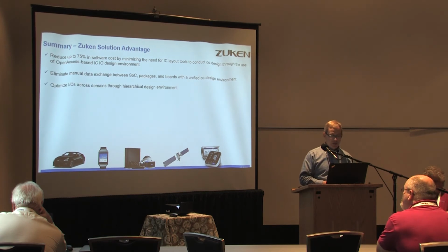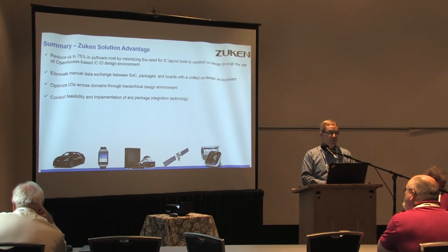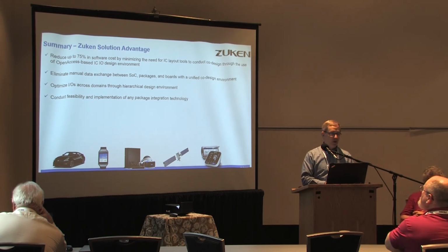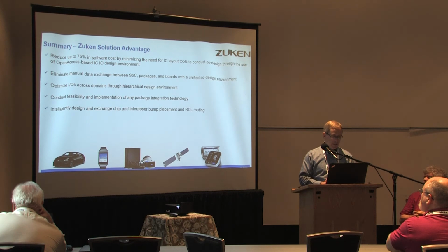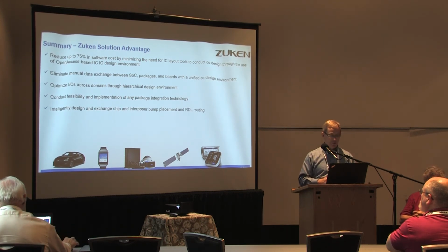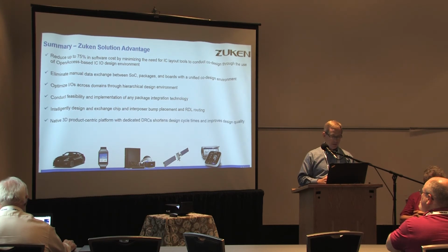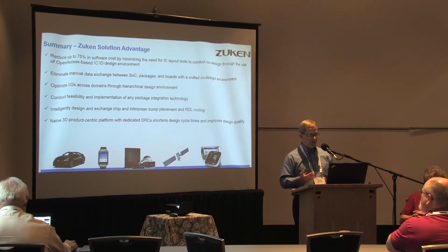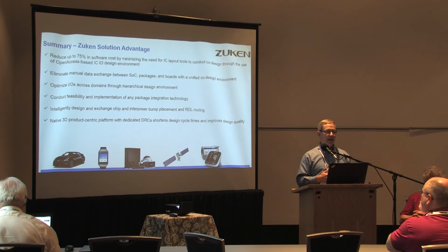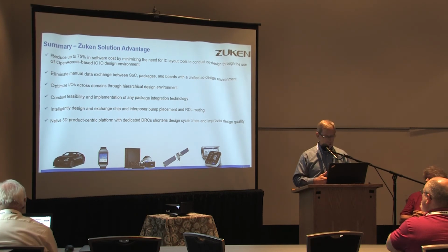We optimize I/Os across the domains through hierarchical design environment. And then we conduct feasibility and implementation of any package integration technology, whether it's simple wire bond design or complex SIP or fan-out type designs. We can intelligently design and exchange the chip and interposer bump placement and RDL routing. And then the 3D design environment just gives us an easier way to check for DRCs and shorten our design cycle times.